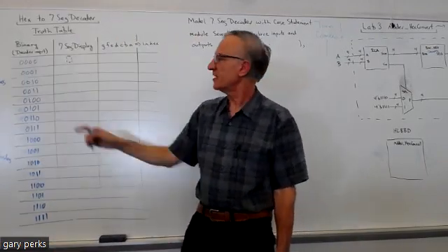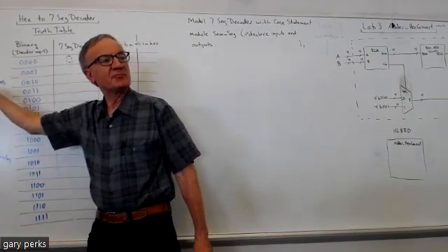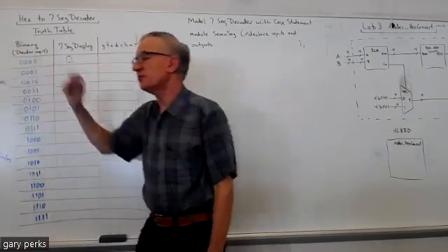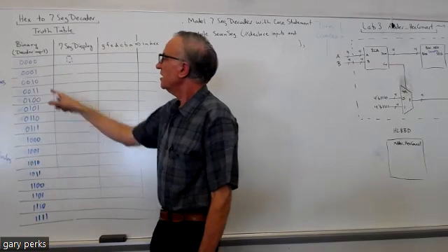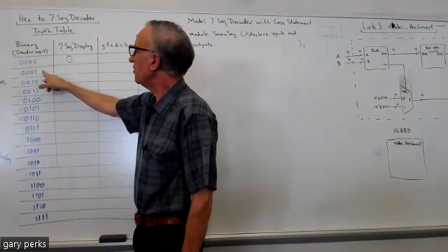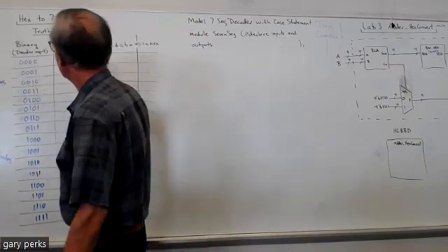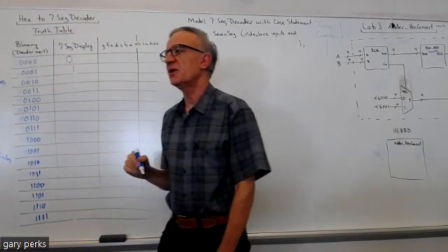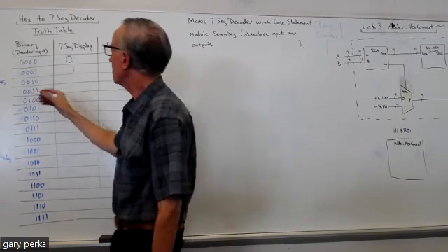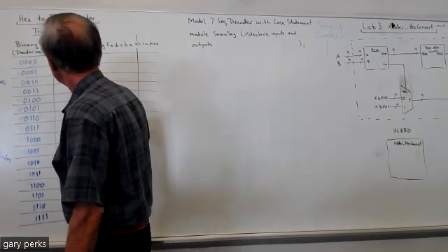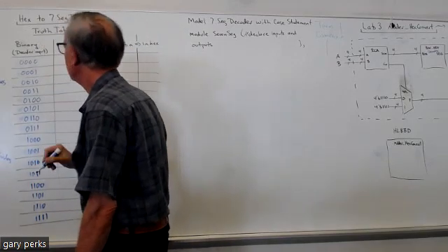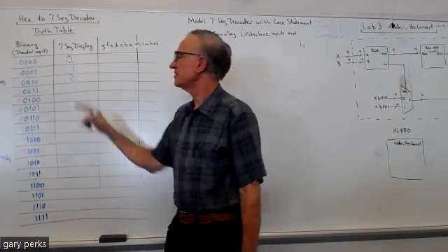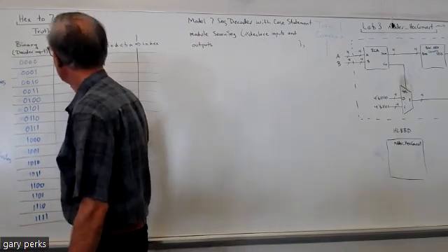If I just light up the perimeter LEDs, that will show a 0. If I've got a binary 1 going in, I would just want the B and C segments. That would show a 1. If I got a binary 2, I would want these segments still. And you see I would do that for all the combinations, for a 3.